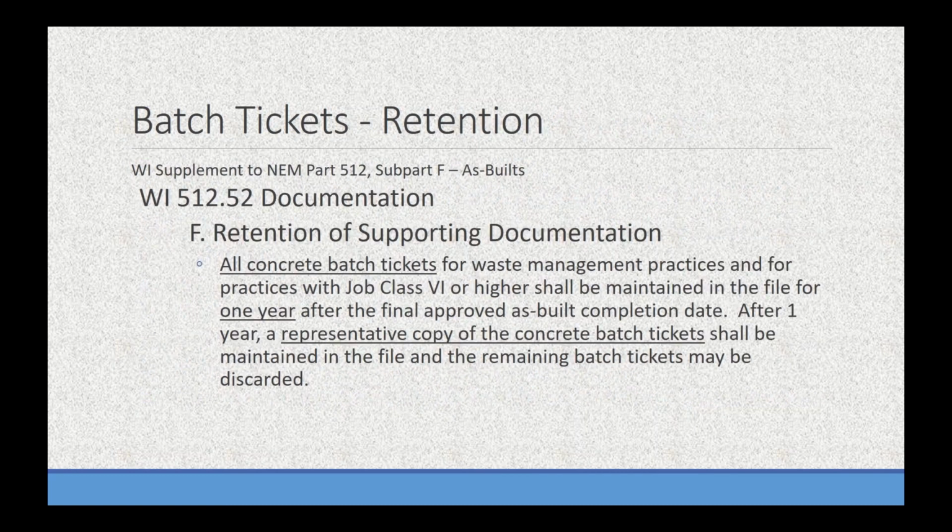We get plenty of questions on this. We've had them at several technician meetings. How many batch tickets do you have to keep? How long do you have to keep them? If it's an NRCS funded job, and probably just a good general rule of thumb for other jobs, we've got this Wisconsin supplement to the National Engineering Manual policy that states all concrete batch tickets for waste management practices and jobs that are class 6 or higher shall be maintained in the file for 1 year.